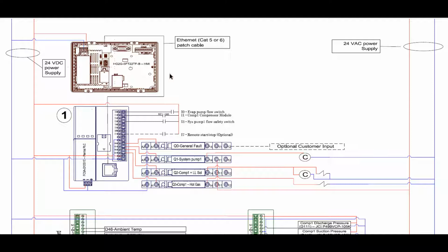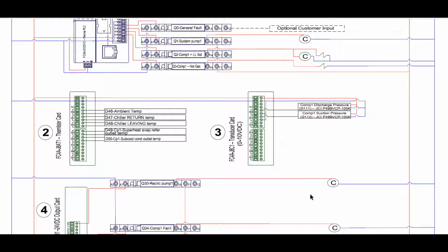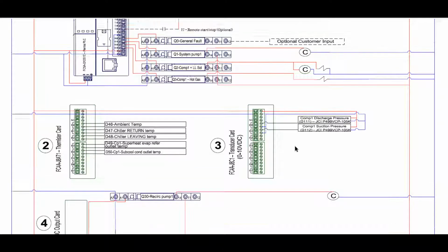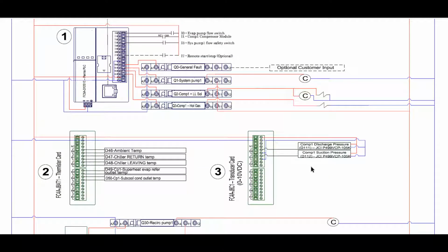When the compressor starts, the PLC is reading in real time what the discharge pressure actually is. It's going to hold the output for the fan motor. You'll notice here we have two outputs, and this particular chiller has two fans, so you'll have two separate set points. It'll allow the head pressure to rise until you get to set point plus differential.